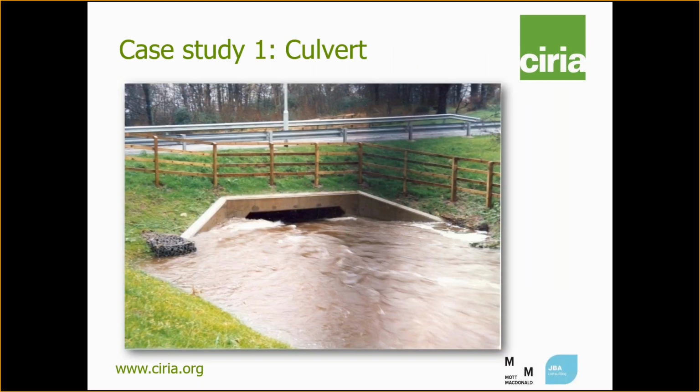Okay, thank you, Amanda. I'll just quickly go through three simple case studies, starting with one on a culvert. The new manual doesn't actually have any standard details for either culverts, screens or outfalls. And that's for the simple reason that, as it is advocating a systems and risk-based approach, there is no universal solution to a wide range of problems.